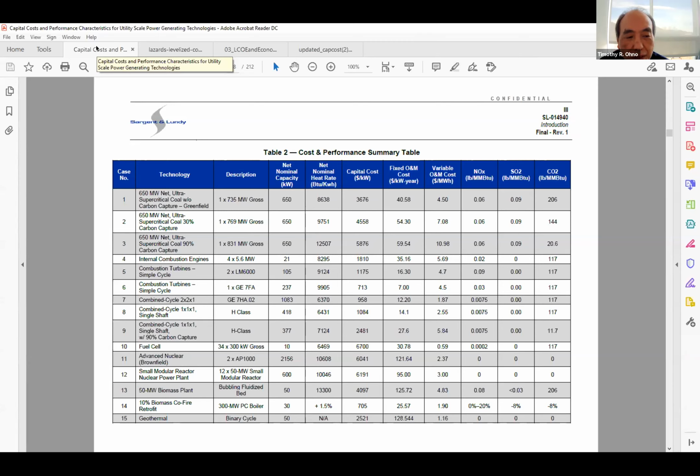So in the case of 3, I have a nominal capacity of 650 kilowatts. So in 1 year, if I multiply that by a little bit over 8,000 hours, then I should be able to figure out my kilowatt hours, right? What's wrong with that? That's assuming it's at 100% capacity, but probably isn't.